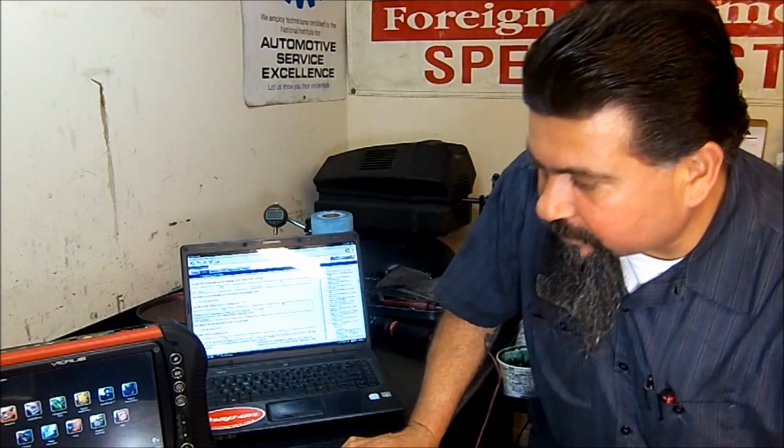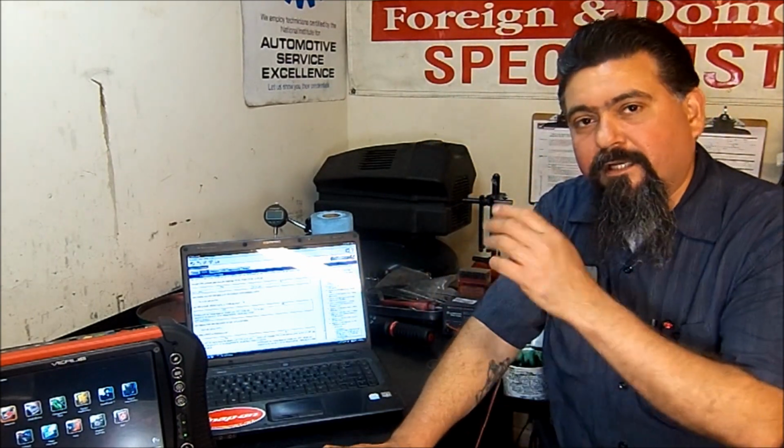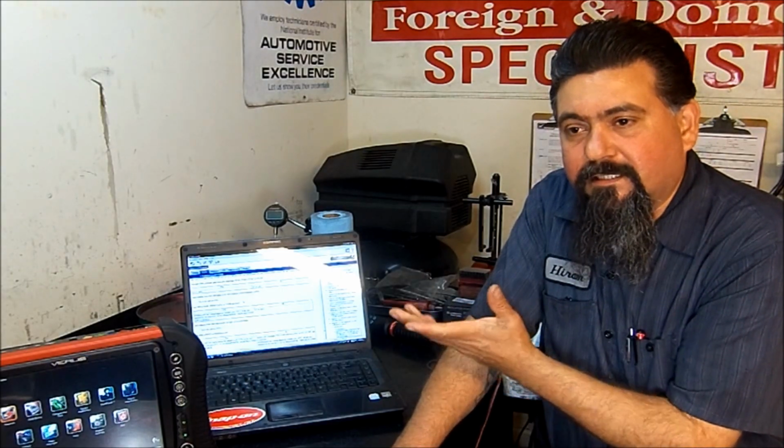Okay, so what's our conclusion here? I already went and test drove it, and all of my signals are good. The code 2106 did not come back. It's not in forced or limited power mode.